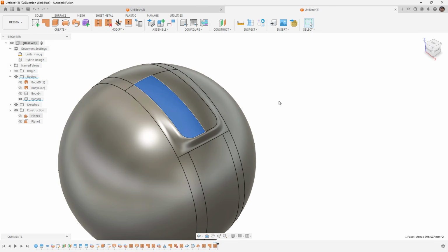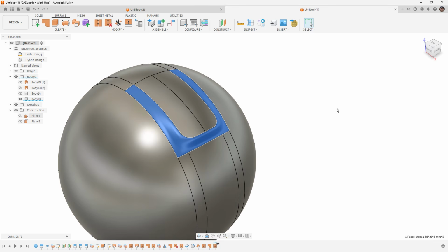And generally, if you can work with symmetry, so for example, if the left and right side of this are exactly the same, work with half of it, because that gives you the ability to build tangent, extruded surfaces that can be tangency references. And that will simplify the process in a lot of cases in terms of building the curvature out. Now, at some point, having both sides and patching, like for example that surface, is going to produce better results. It's going to be a bit easier.